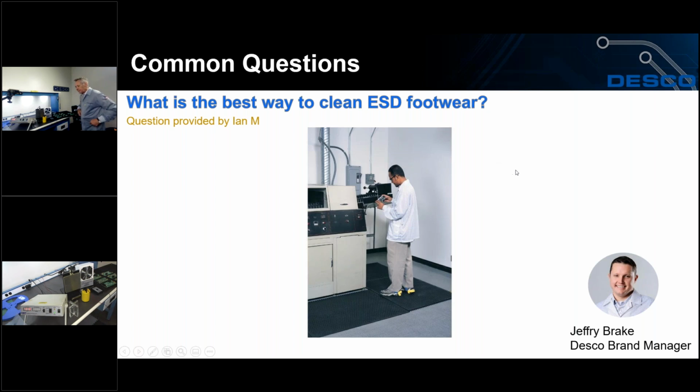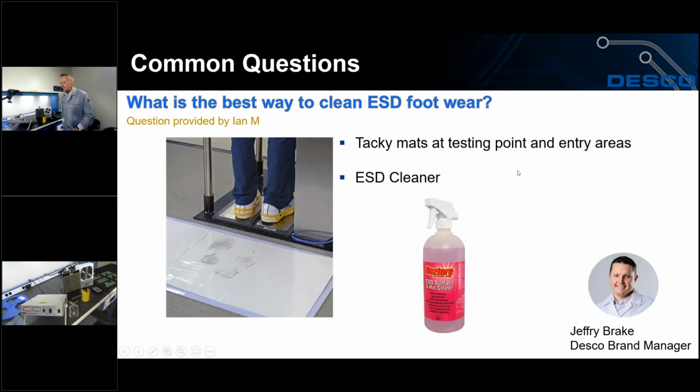What's the best way to clean ESD footwear? For daily cleaning and periodic cleaning, you can use a tacky mat. You can put these in front of your testers or at entryways into the work area. That'll remove most of the dirt and grime that builds up on foot grounders. Foot grounders are pretty durable products, at least the ones we make are. They're meant to be walked on. They're meant to get a little dirty. Most of the time, they'll still function just fine for testing and for use in the EPA.